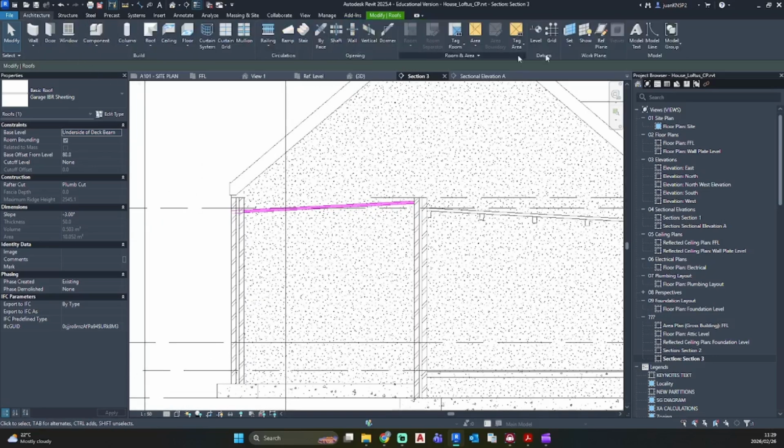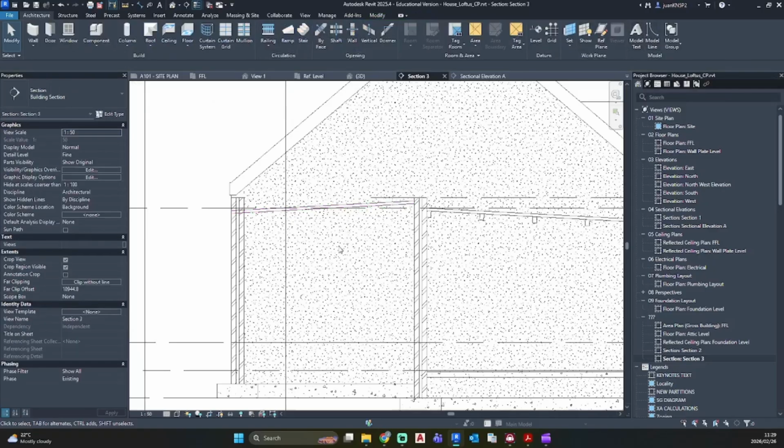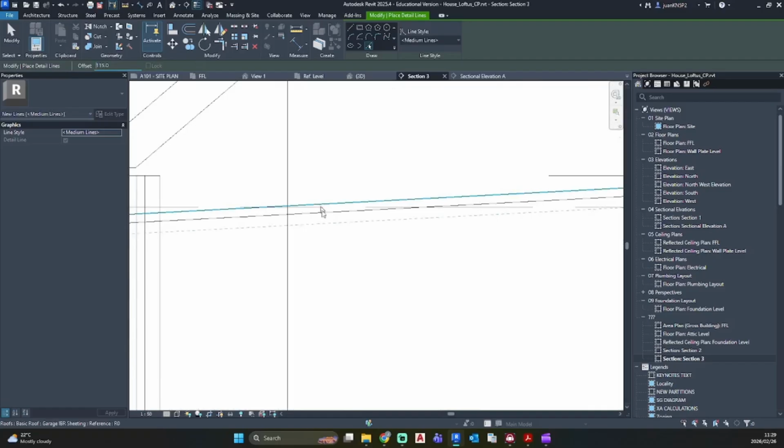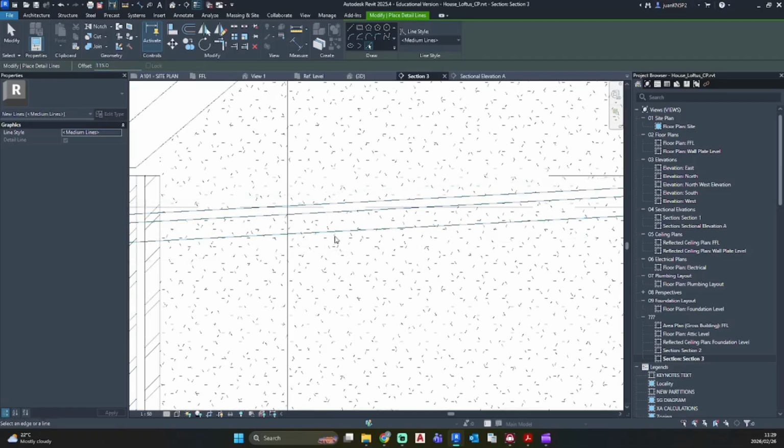I'm going to go architecture. Right, let's draw a detail line, rather DL for detail line. Create an offset, and this is also 75 by 115. So I'm going to go offset 115 just to get a rough idea of the structure. So there we have the bottom of that, and now we need to do another one for 38 for our brandering and 12 for our ceiling.